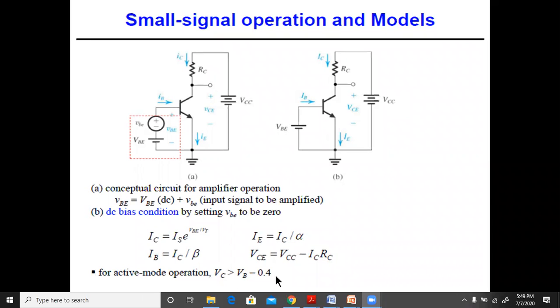So the 0.4 might be the minimum voltage which is needed to drive the transistor to on. Ideally it might not be 0.4, it might be 0.6. So the value of VB should be greater than ideally 0.6. He has taken 0.4. Do not bother much about this value. Okay, so this is the DC model, whereas this will be the instantaneous model, where we have joined both the components of AC and DC together. All these values are DC values over here.